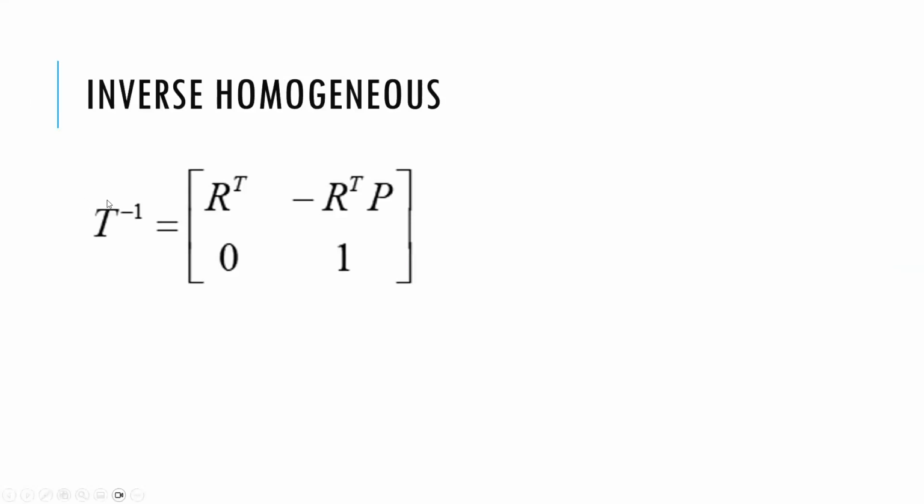So sometimes we want to take the inverse of that, first for inverse kinematics. Since this is a special 4x4 homogeneous matrix, there's a shortcut. You could take the rotation part and transpose it, which means the columns become rows and the rows become columns. And the position vector would be the negative R transpose dot product. So you have a 3x3 dot product with a 3x1, and that will give you a 3x1 coming out of there. That's a shortcut to doing a transformation as well. And then also you can use your basic calculators to do this transformation as well.